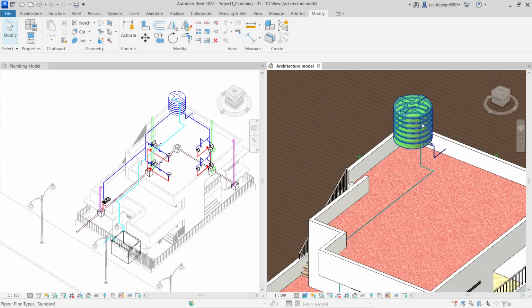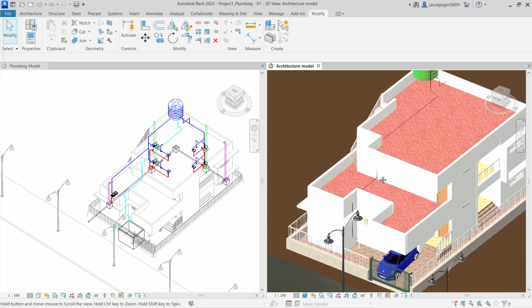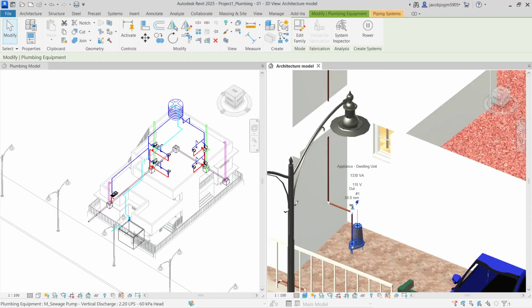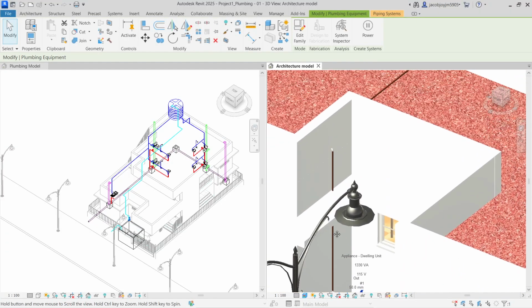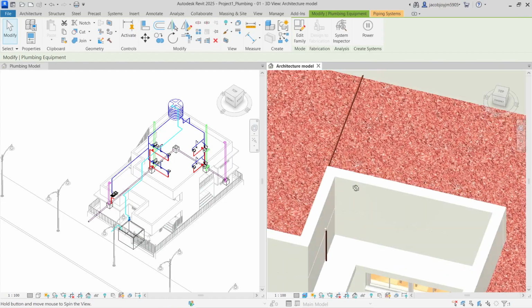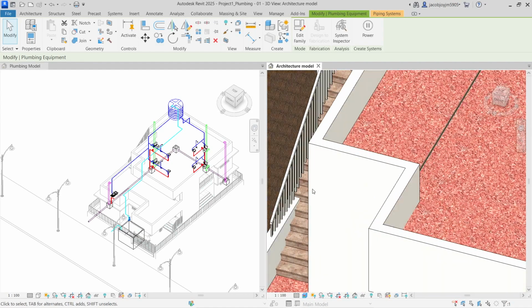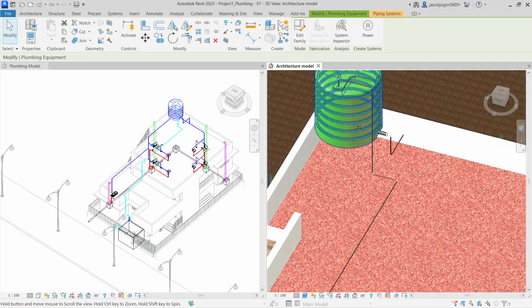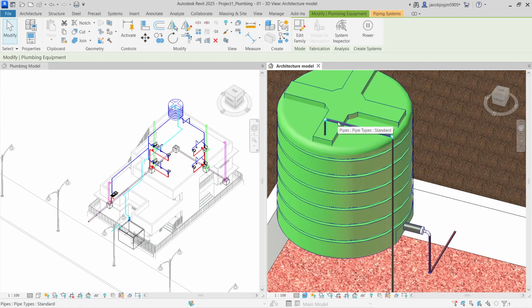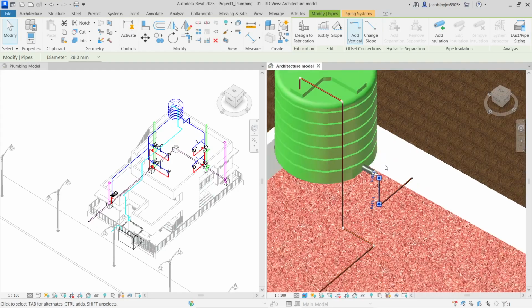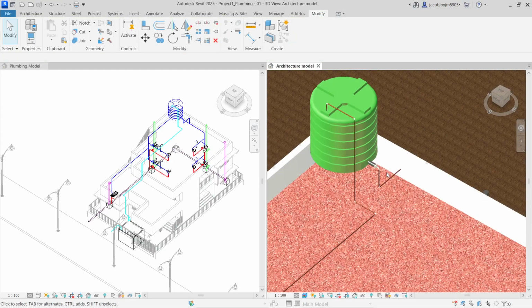Once you place the water tank, then you can route the motor and the vertical pumping routing also. The pipe is coming till here and it goes to the water tank. Then we have the outlet. The outlet pipe size I have given is 28 mm, for all the inlet and outlet pipes.